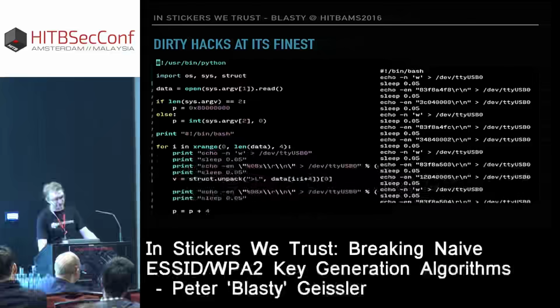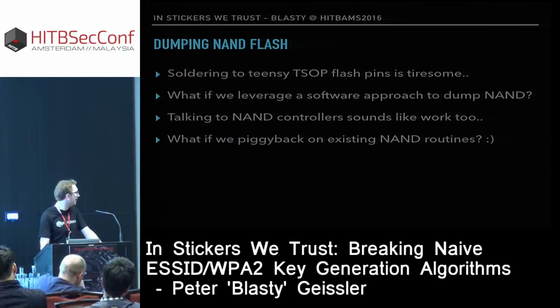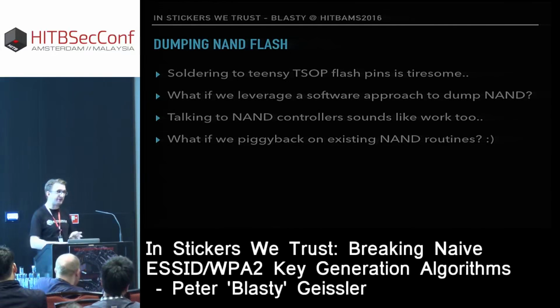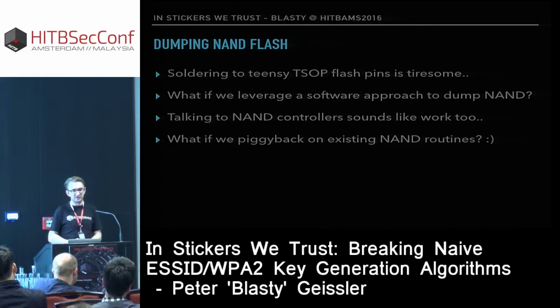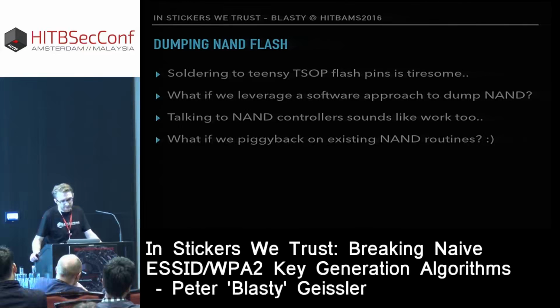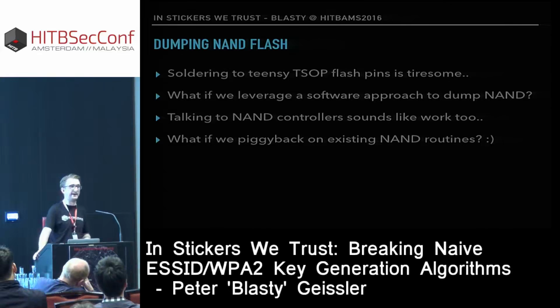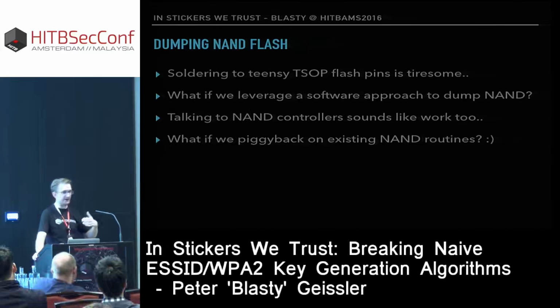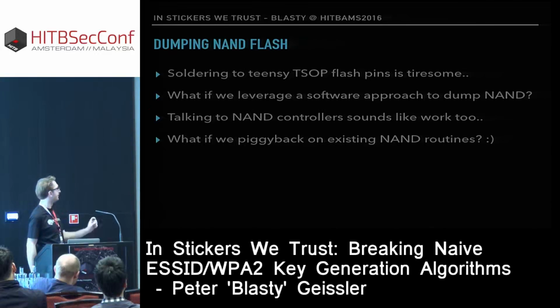And I was like, well, I can leverage the same thing to dump the NAND flash maybe. But then I have to talk to the NAND controller, right? So I need to know what NAND controller it is, what bits do I flip, and what registers in order to trigger a sector read from the NAND flash, and then get the data out. And I mean, it sounds like work. So what if we look for existing NAND flash routines that are already part of the bootloader, and we just jump into those routines and let them do all the heavy lifting for us, and we get the data out. Then we're still left with the problem that we need to get the data out of the system. But of course we have our serial port, so we could spit the data back out over the serial port.